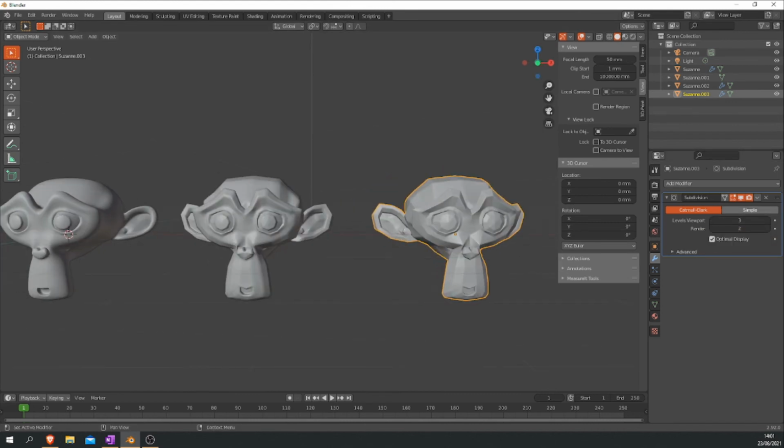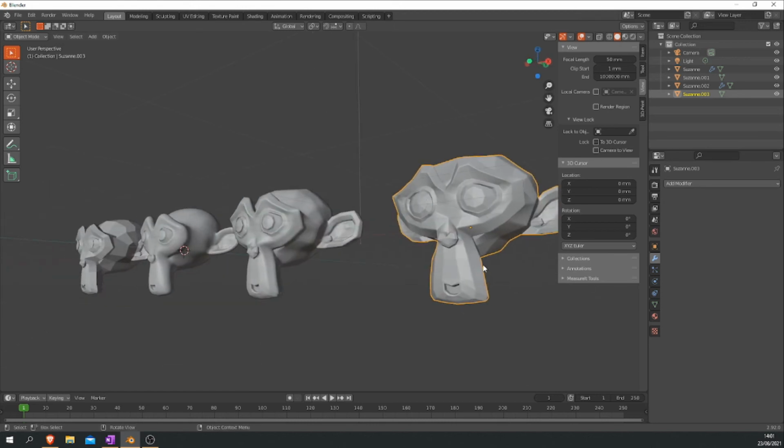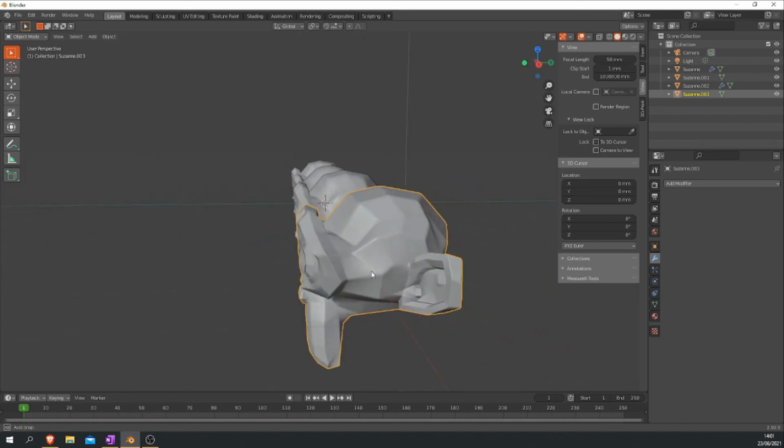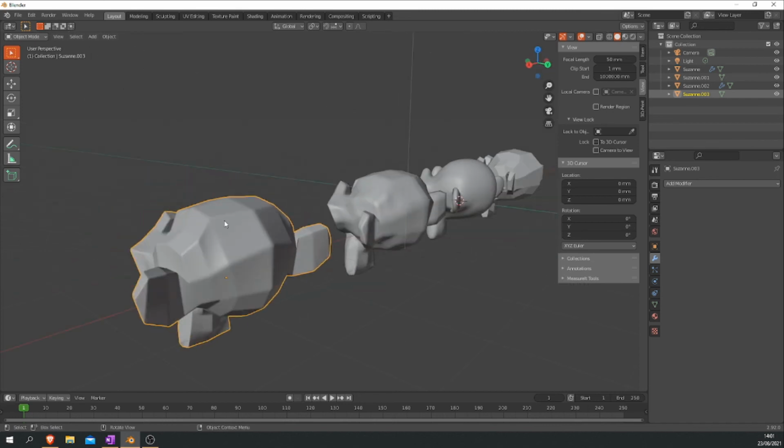You can see it has done something a little different where you apply all of these singularly. Let's say that's just the Catmull Clark. That is your simple, and this is your simple and your Catmull Clark. You can apply both of those together to get maybe an in-between version, if you really wanted to. As you can see, the curved surface there is way smoother. This is smoother, but you still have your face preservation as well.